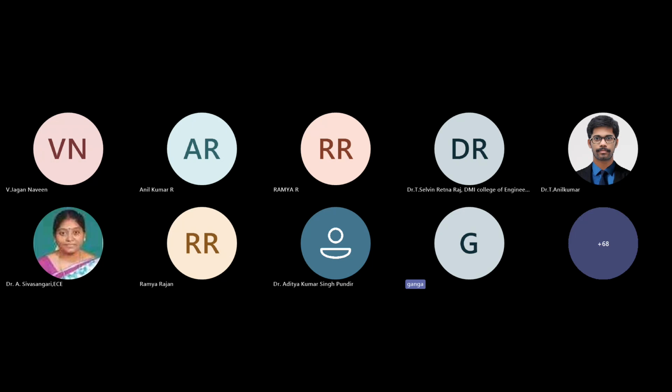Again, here I have shown only the ring oscillator. For example, if you take amplifiers, when you want a high gain amplifier, the best way is to cascade low gain amplifiers so that you can get higher bandwidth as well as higher gain. So depending on the type of design that you want, you can experiment with different techniques.